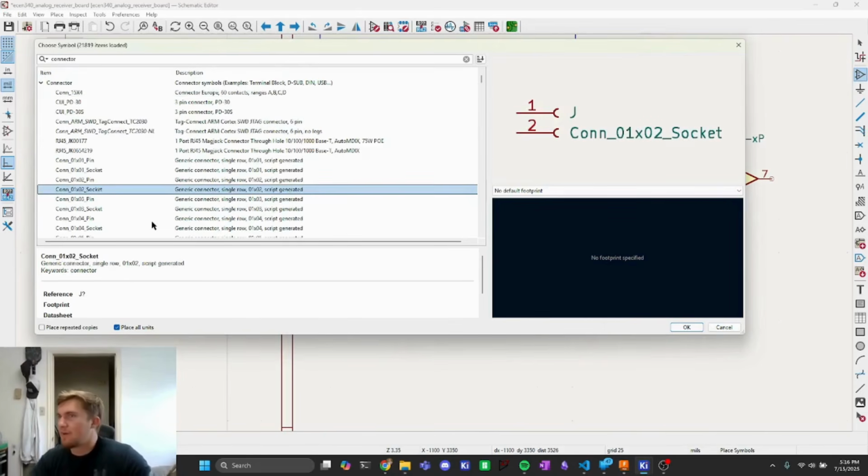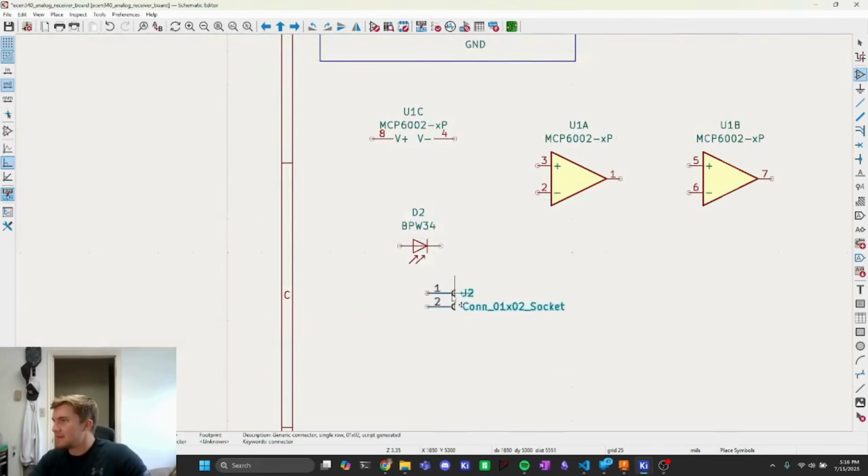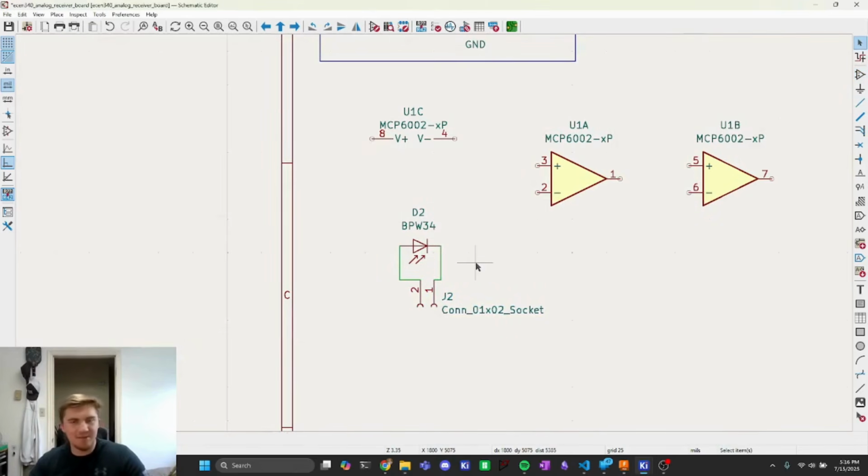So go ahead and whip out a 1x2 socket, put them below, wire the anode to one end, the cathode to the other, and now you have a socket in parallel. Now later when you do the custom project in 390, if you wanted to add more sensors to your gun, or a sensor to a hat or a vest, that way you have more than just the one sensor on the gun, all you have to do is wire a single diode in parallel.